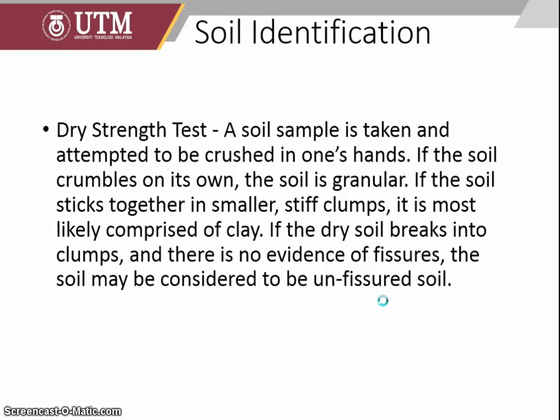In addition, you can also do the dry strength test, a very simple test that just needs us to take the soil at its natural moisture condition. So try to crush the soil. If it crumbles on its own, it is granular.